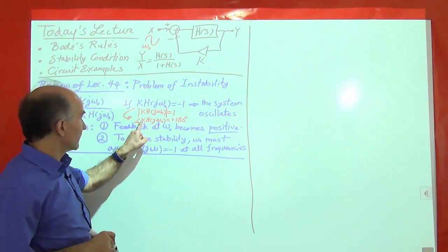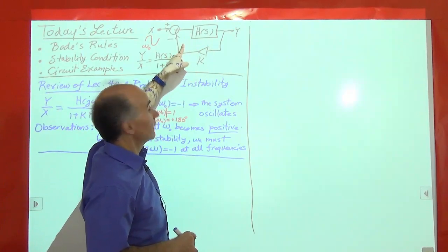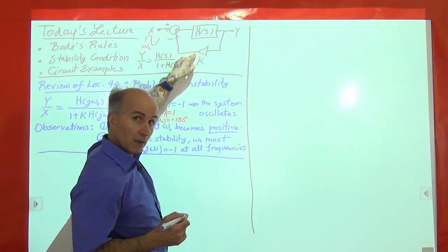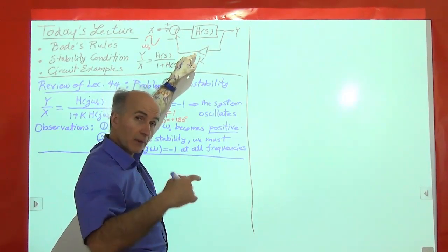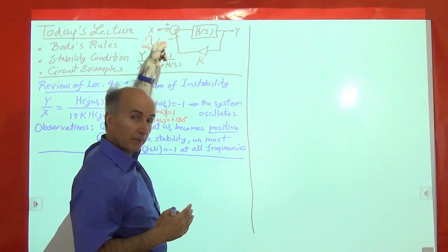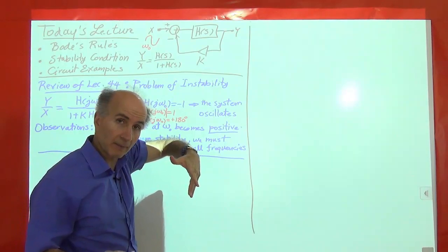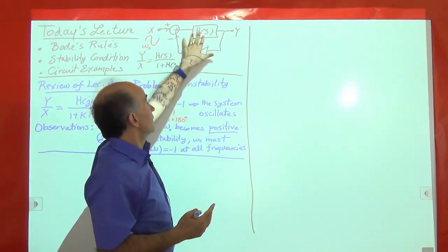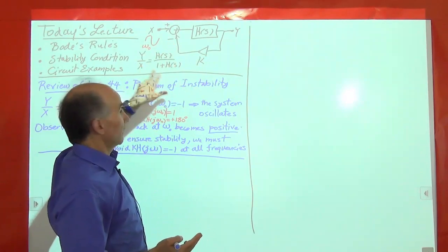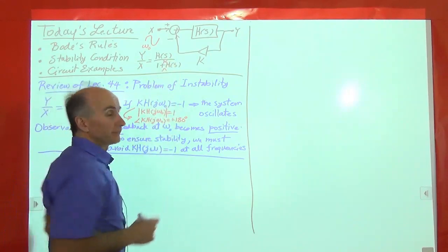So what this tells me is that the phase shift associated with this loop here is 180 degrees. So as I start from here and I end up here, the signal is flipped vertically, so that causes this overall positive feedback. Okay? We thought we designed the negative feedback system because we thought this times this was positive and this was negative, and that's how we arrived at this transfer function, while there's a k missing here.